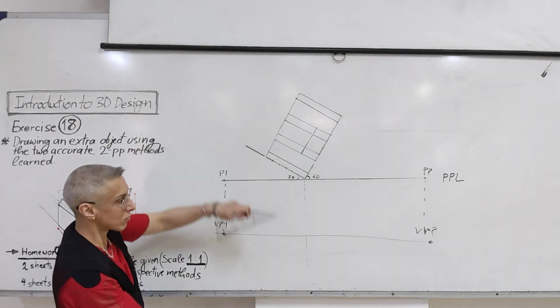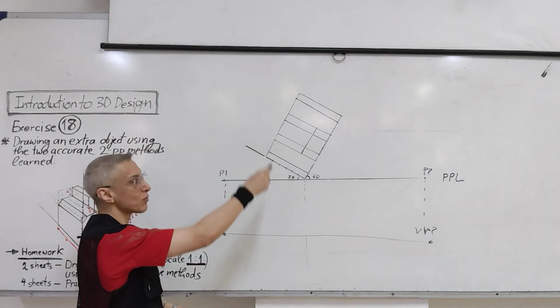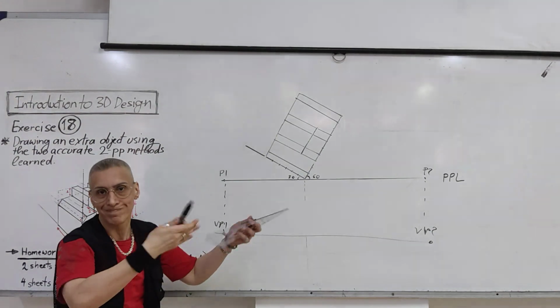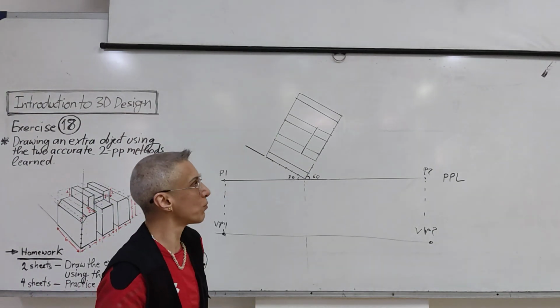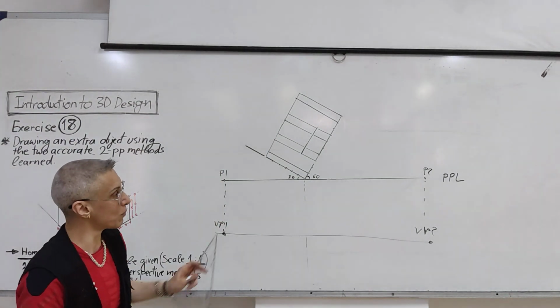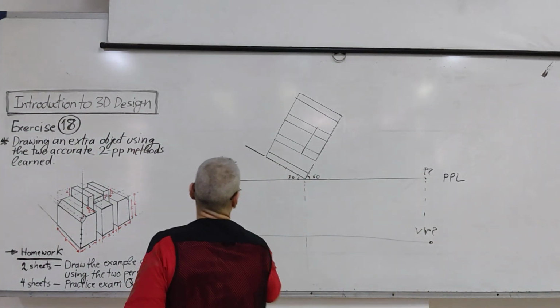Depending on where you want to put it, far away, close to the horizon. And then you will start connecting the points to the station point, and then straight lines down, and continue the drawing, okay? So what I wanted to show, just the top view, how to approach it, because this is important. The rest, according to what I explained the previous class.